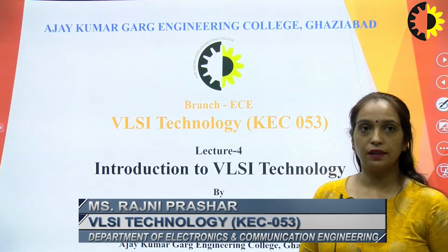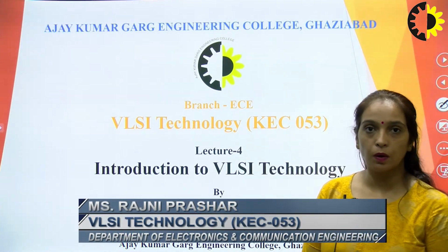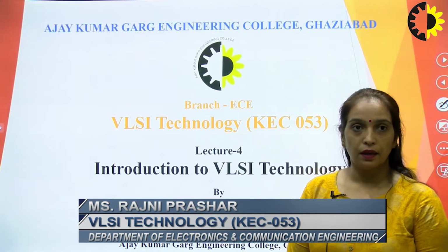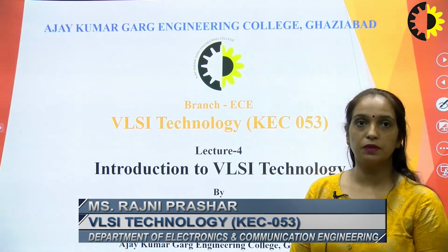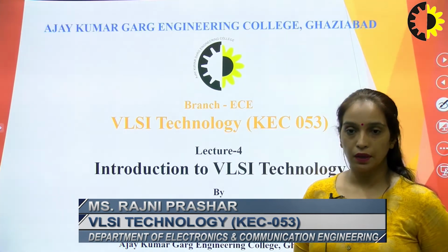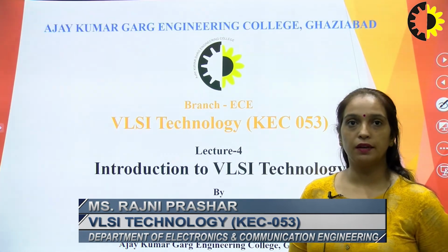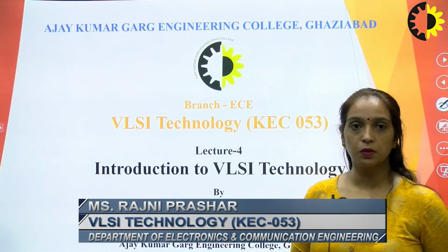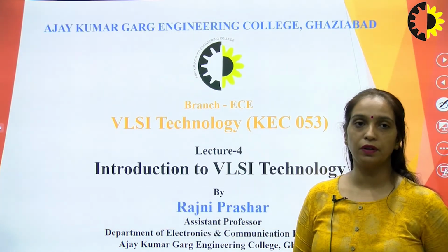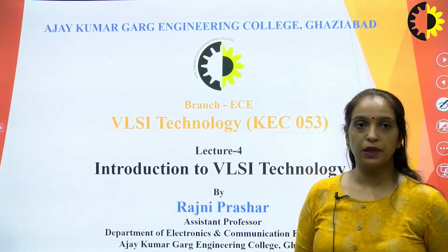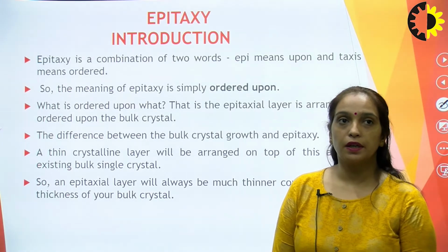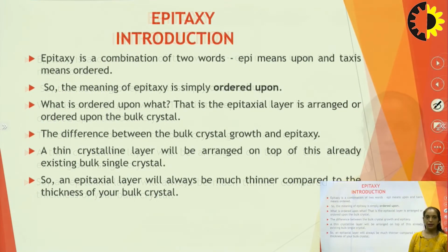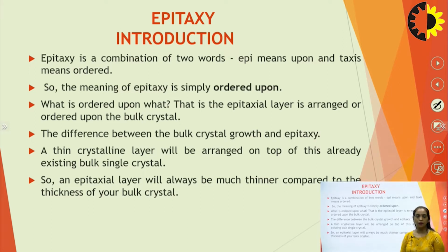Till now we have studied the crystal structure, how the silicon crystal looks, how that silicon crystal can be used to form wafers, what defects are present in a silicon wafer, and how that wafer can be polished and further processed so that we can use it as a base material for IC technology. In this lecture we are going to study the next layer, the epitaxy layer, which is used to grow on the bulk wafer, on the bulk material.